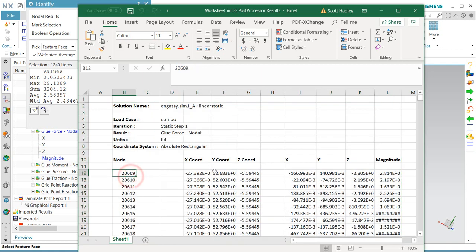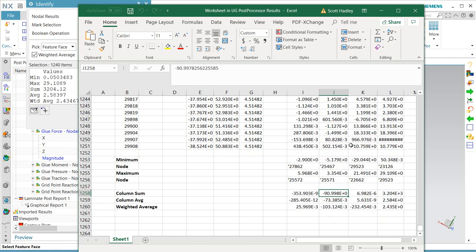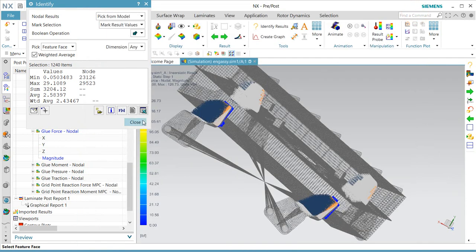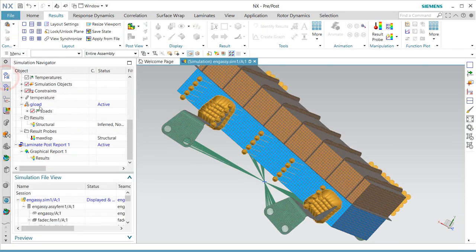And what I'm really interested in is most of our reaction force through the glue is going to be due to our G load, but you can see our node as well as XYZ location and XYZ reaction force. You can see the reaction in X is pretty small as it is in Z, pretty close to 0, but Y, here you can see it's minus 91 pounds. That's going to be an important number. Let's remember that for some other things that we'll do next. So minus 91 pounds is due to that 10G load mostly on our electronic box.